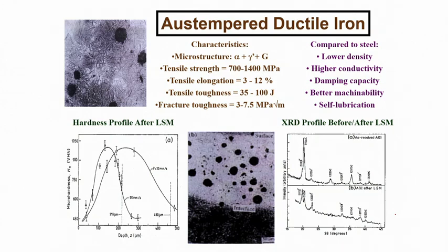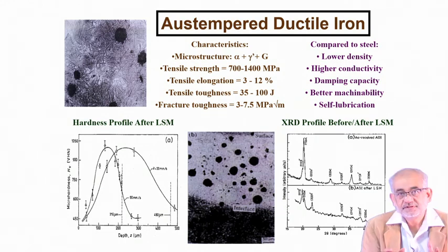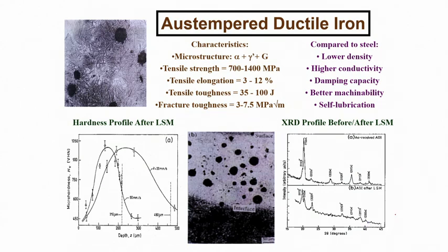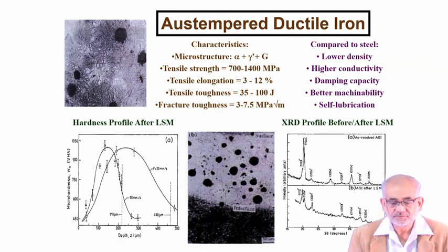If you recall, by cast iron what we mean is that at some point during the cooling process, from melting to solidification, we must intersect the eutectic isotherm. So we end up getting ledeburite, a combination of cementite and austenite, and subsequently the austenite transforms to pearlite. So we end up getting transformed ledeburite at room temperature.